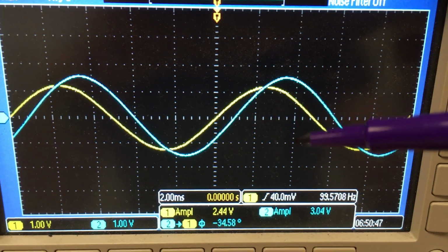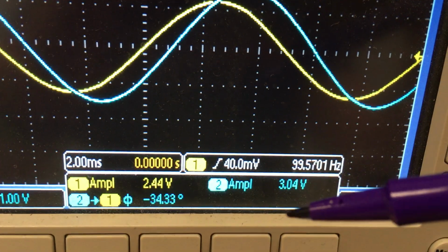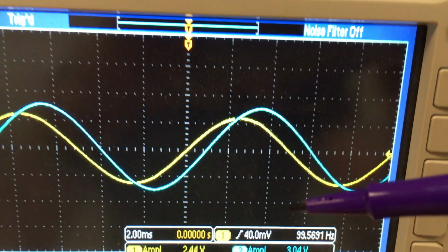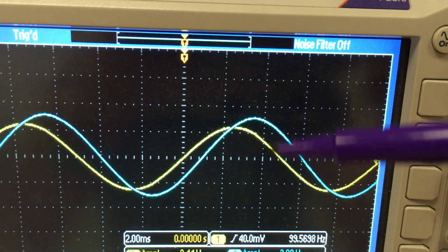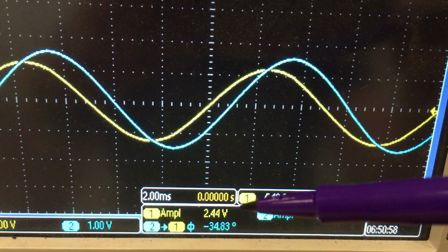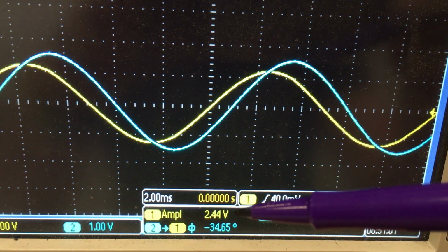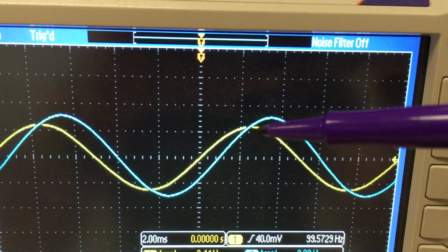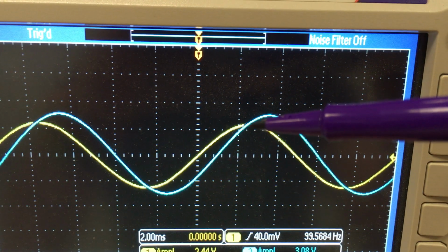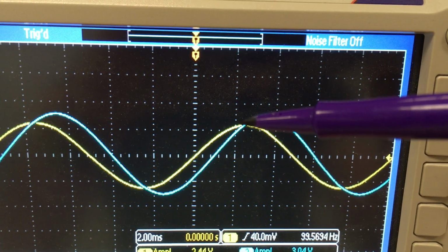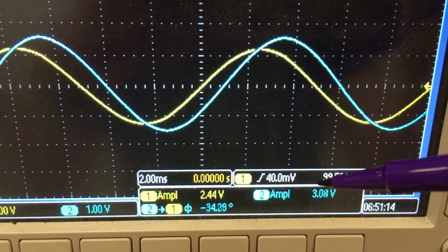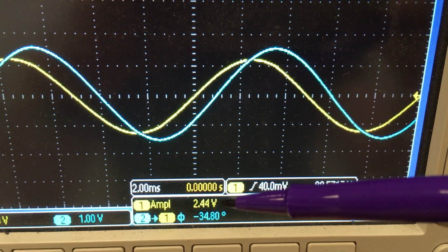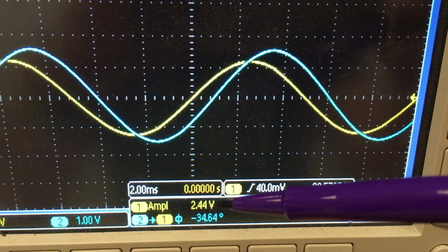The other thing we're seeing is that if you look at the blue amplitude, that's about 3.4 volts-ish, or 3.04. That's the blue, so that's a little taller, and a little shorter is the voltage signal across the resistor. And that suggests that the other things in the circuit, primarily the capacitor, has sort of an effective resistance that's using up a portion of the voltage, the difference between the whole thing applied to the circuit and what is being dropped by the resistor itself.